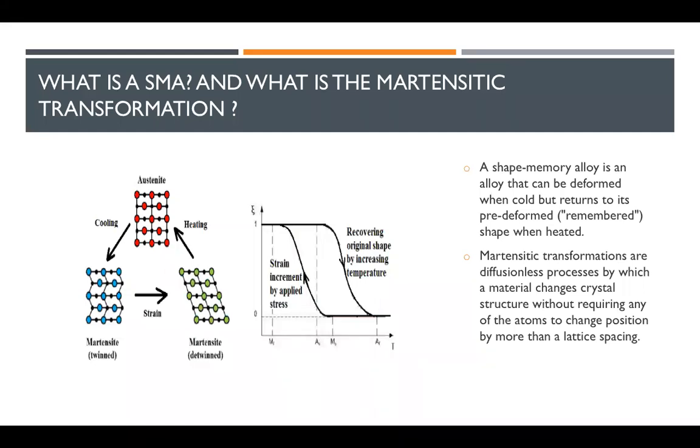Maybe some of you are already familiarized with the subject of shape memory alloys, but for those who are not, shape memory alloys are unique materials that have the ability to achieve great deformations and to return to their predefined shape after unloading or after heating. It is a very straightforward concept. The material is basically allowed to undergo a transformation because of a process named martensitic transformation. This martensitic transformation can be produced by two means: changing temperature or by the action of stresses.